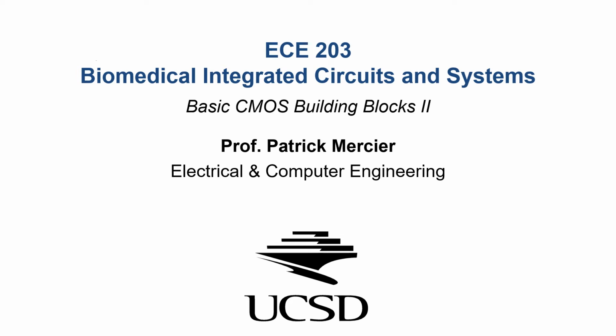Welcome to ECE 203. This is the second lecture on basic CMOS building blocks. At the end of the previous lecture, we were just discussing the common source amplifier and what some of its metrics were in subthreshold and in above threshold. And we found that for an interesting case in subthreshold, we actually didn't have, as a designer, good control over the gain, which is an interesting proposition. This is not what we're used to if you are a typical analog designer operating in above threshold.